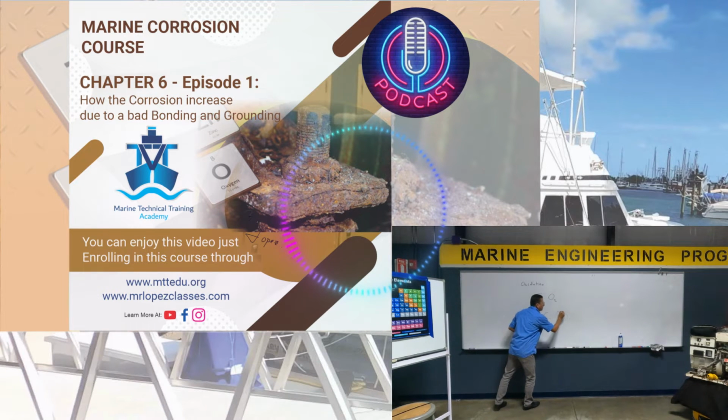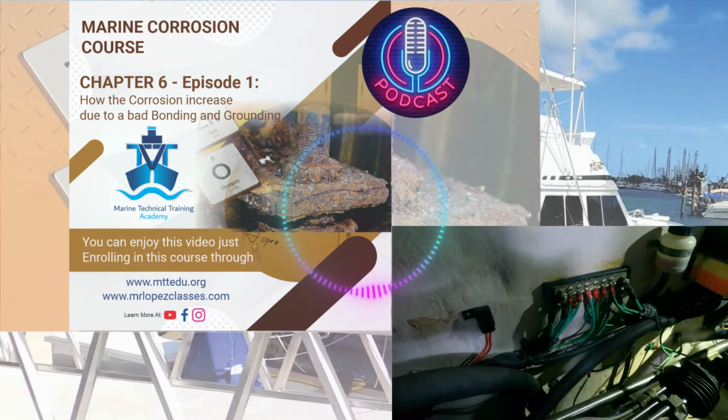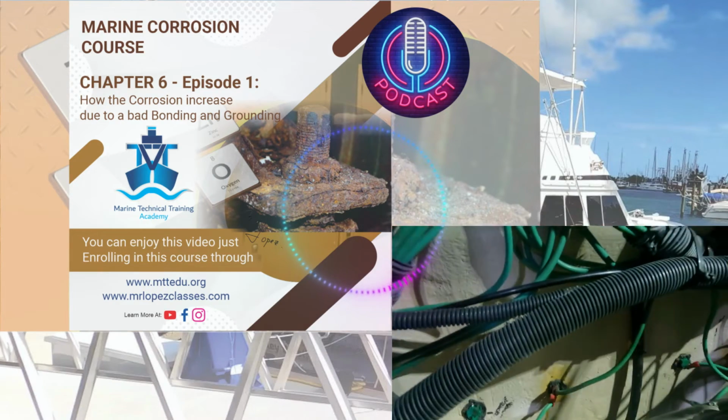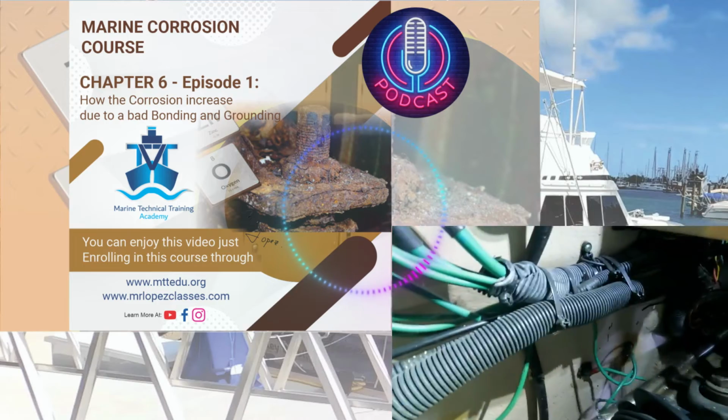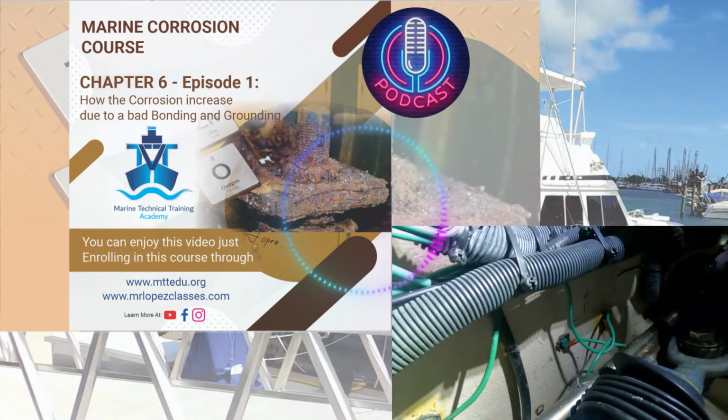Oh, I have 6 groups of batteries in my boat. No problem. The only thing you need is to verify that the negatives of all those groups are connected together with the main negative bus bar, and the main negative bus bar with the bonding conductor. This is the most important part if you want to have the boat properly protected.